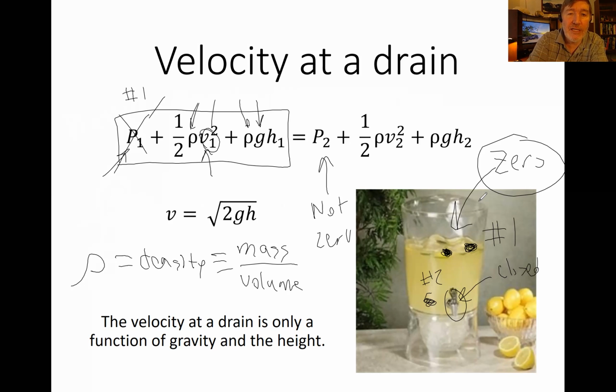Okay, so Zaid remembers that 9.8 is the number that we used in physics, but be warned, that number only applies if you're measuring in meters per second per second. If you're using American units, which is what most engineers use, American engineers don't usually measure distances in meters. They usually measure distances in feet. So if you're using American units, do not use 9.8. You need to use 32 because the acceleration due to gravity in feet per second per second is 32.